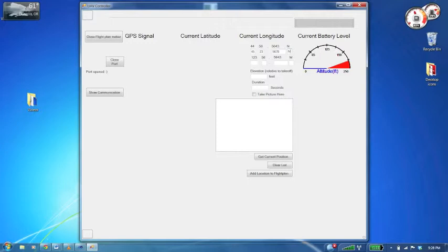It is important that you enter the correct value in each dialog box, as if you were to enter a letter in a number field or a number in a letter field, once you try to add this coordinate point, it would not allow it, and it would ask you to go in and change the error. This elevation box is relative to the takeoff elevation. So I'm going to go ahead and enter 100 feet.